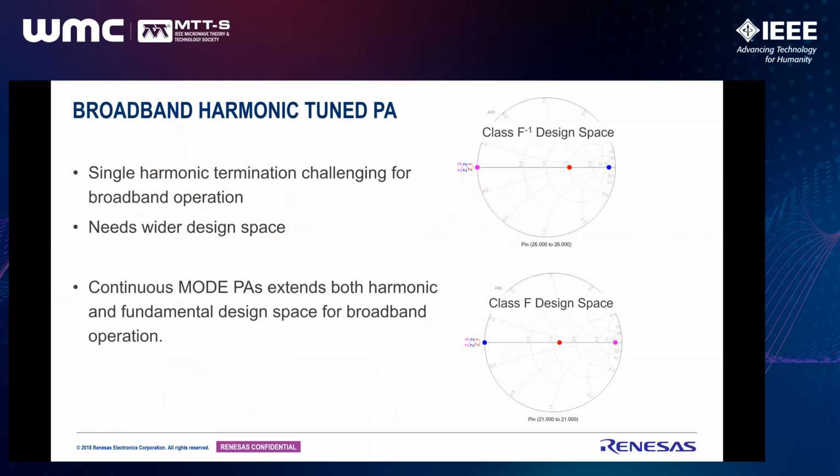So far, the PA classes we have been discussing are, you can see, single point of impedance termination. But the point is, it's very difficult to realize a perfect short or perfect open for a broadband operation.